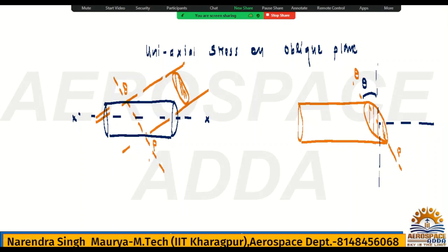Now this is the vertical, you can assume this is the vertical. So from the vertical it is making angle theta. Now if you want to get the normal stress, normal stress means exactly normal to the plane. If this is the plane, then normal to the plane means this. So normal to the plane you will get one stress called normal stress. It is very clear, simple trigonometry. Because this is theta, this angle will also be theta.